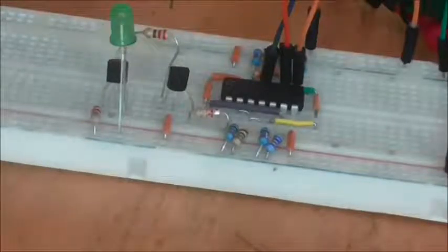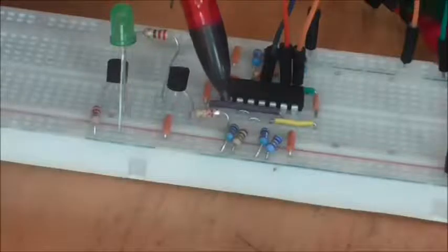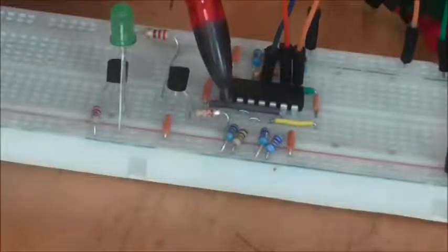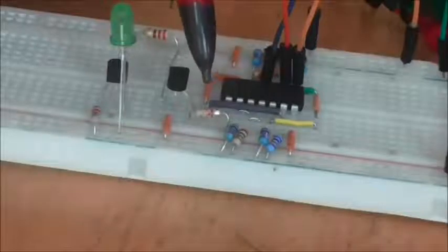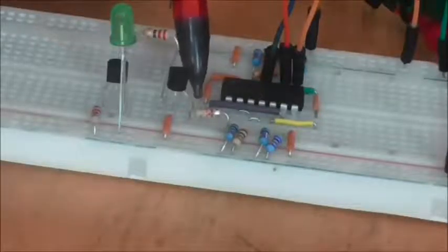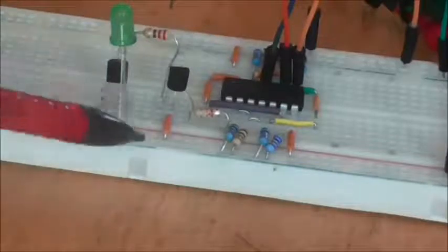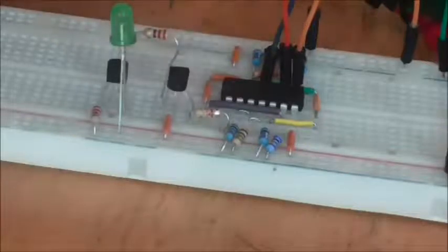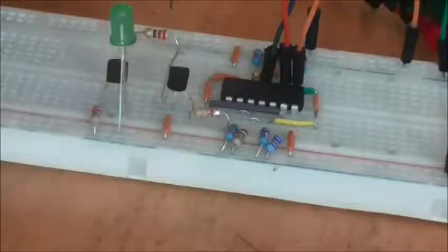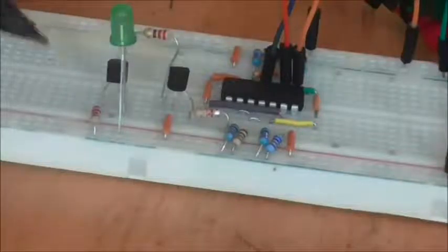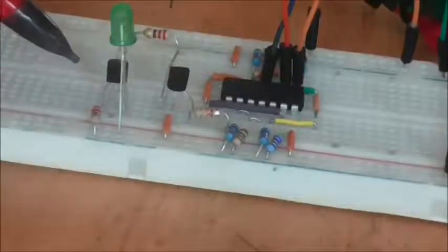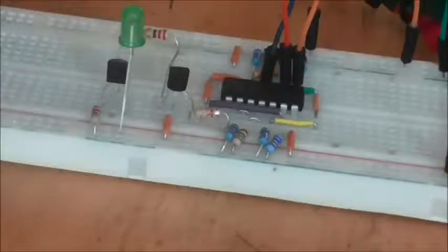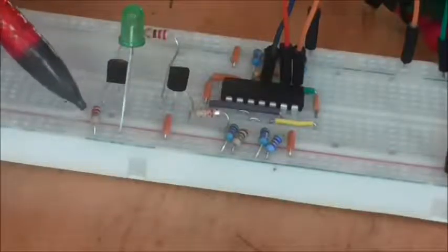And what we've got is the output here from our last NAND gate going through a 22k resistor to the gate of the thyristor. The anode of the thyristor here is put permanently into the 5-volt rail, and the cathode of the thyristor here is attached to a 220 ohm resistor, which in turn is attached to the base of the transistor. And this time I've collector loaded this LED, and I've sent the emitter to ground.